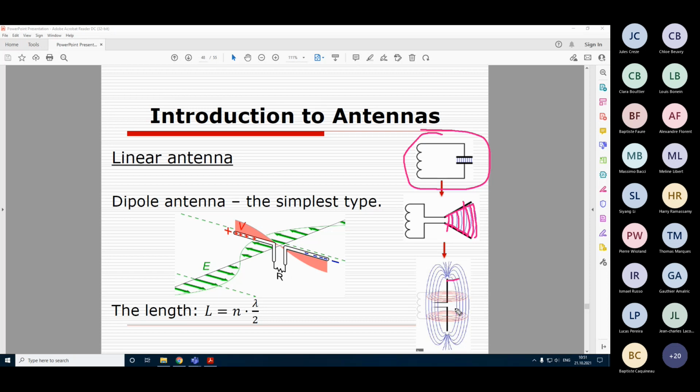The size of this metal part is actually related to the wavelength. For example, lambda divided by 2, lambda divided by 4, lambda divided by 10. However, as has also been mentioned in the previous video, especially if we have many antennas, such as in a MIMO case, it's very important that the length of the antenna is related to half of the wavelength of the signal.